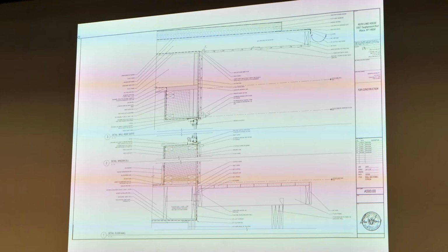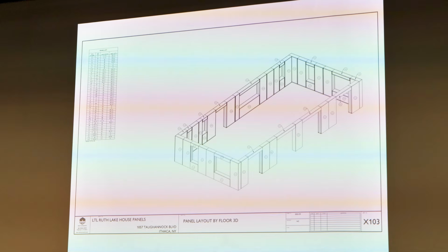The wall system is compressed straw. The floor is timber HP. It's filled with essentially a timber fill. It's an all-wood system. Uniquely using lime plaster as the air barrier on the inside, right?